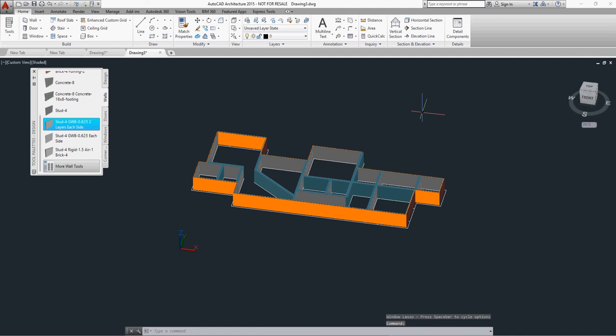All right. And if I go to a 3D view, you can kind of see the interior. And I can use the Extend tool. And I can set everything to a boundary edge and say that I then want to extend that wall. There it went. I want to extend that wall. There it went.